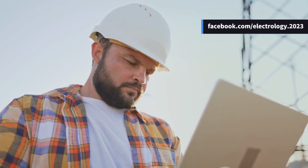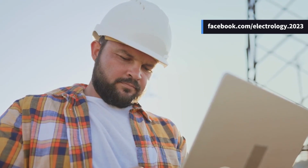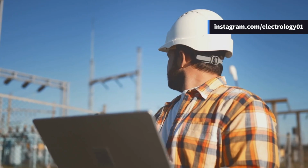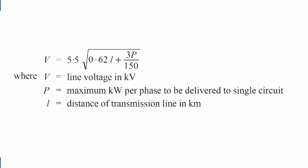These days, instead of calculating everything manually, engineers prefer to use empirical formulas to estimate the economical transmission voltage. One such formula is used in American practice for a three-phase AC system. It goes like this. Voltage equals 5.5 multiplied by the square root of 0.62 times the distance, plus 3 times the power divided by 150. In this equation, voltage is the line voltage in kilovolts. Power is the maximum kilowatts per phase that will be delivered through the circuit. Distance is the length of the transmission line in kilometers.